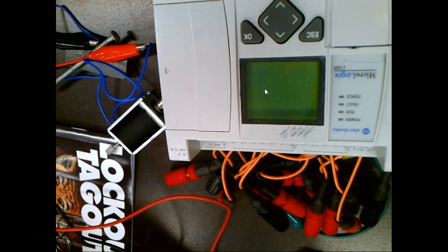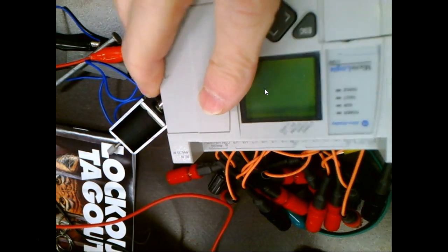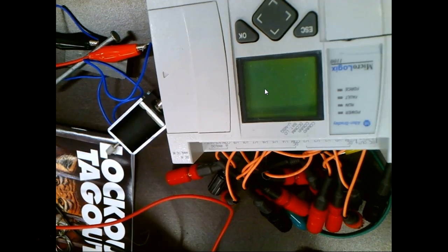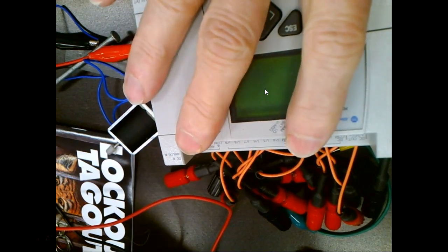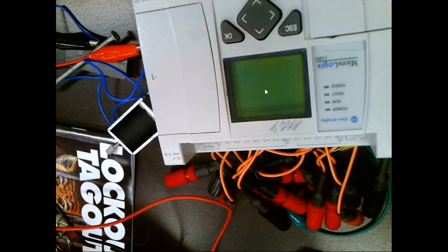But the problem is that we've got some pulse width modulation. I could not run a DC drive off this using pulse width modulation, because we're going to run that around 50 kilohertz, and I cannot switch a relay at 50 kilohertz. So even though this PLC supports pulse width modulation, I can't use it on this one unless I run real slow devices, right? Does that make sense? So relays are great. They do logic.